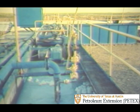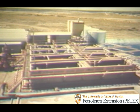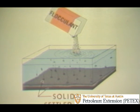These are muds that contain less than 5% by volume solids. Clear water or low solids muds give relatively high rates of penetration. In other words, you can drill ahead faster. Since the water picks up solids during drilling, large settling pits where solids can drop out are necessary. Also, a chemical called a flocculant may have to be added. The flocculant causes the solids in the mud to flock together or flocculate and settle out due to their large size.